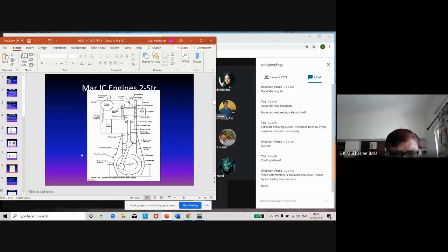Now, in hydrodynamic lubrication, to enable that film of oil to go under the shaft, you need 4 parameters to be satisfied. The number one parameter is the correct viscosity of the oil. The oil cannot be too thick and neither can it be too thin.